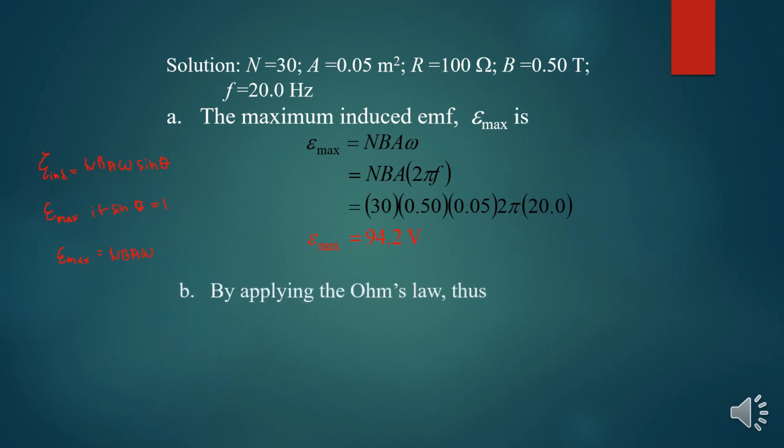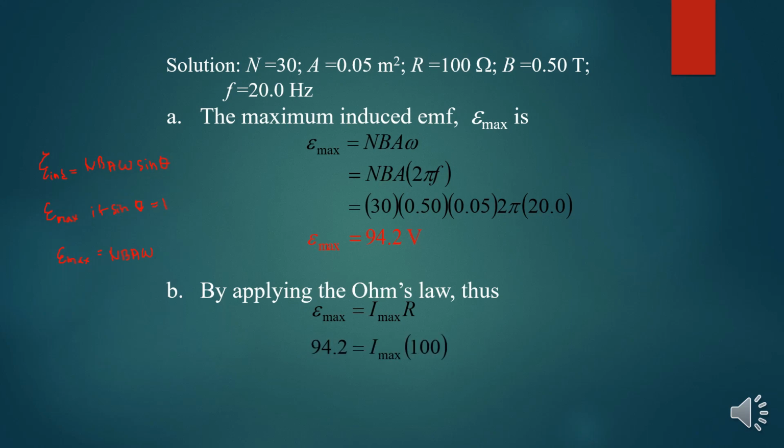Question B. The induced EMF also obeys Ohm's law. So by applying Ohm's law, EMF maximum equals I maximum times R. Therefore, substituting the values, I maximum will become 0.942 ampere.